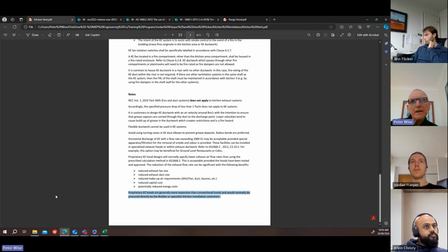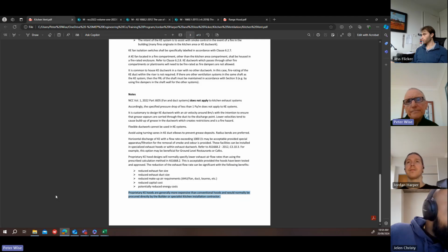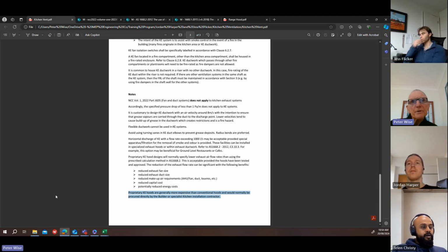So if that's the case, you need to request from the builder details of that hood, which will have drawings of the hood, where you connect to it, and the flow rates for exhaust and supply. It's a very large topic, obviously, and if you have a job with a kitchen hood, you need to determine what cooking equipment is being exhausted.